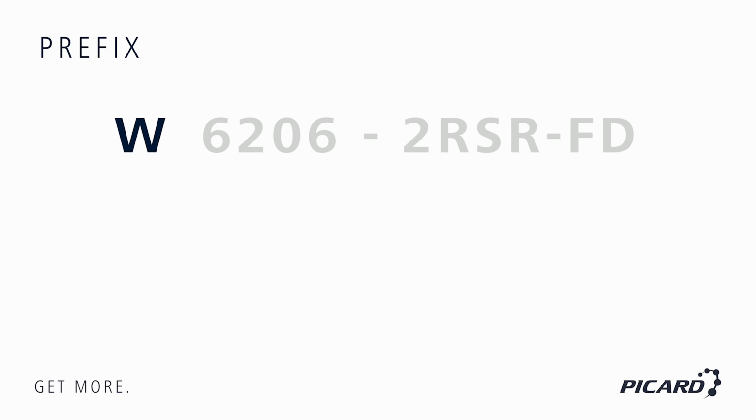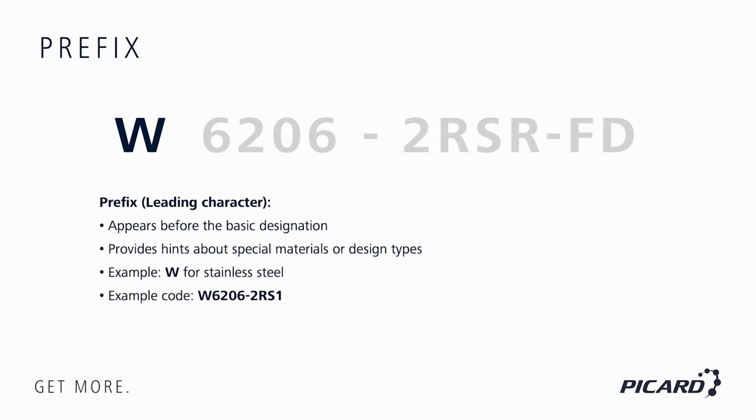Besides the base code, some bearing designations also include prefixes and suffixes. Prefixes come before the base designation and indicate special materials or design features. Suffixes come after the base designation and provide additional information about seals, cage materials, internal clearance, or lubrication. Prefixes aren't standardized and can vary by manufacturer. For example, W indicates stainless steel.